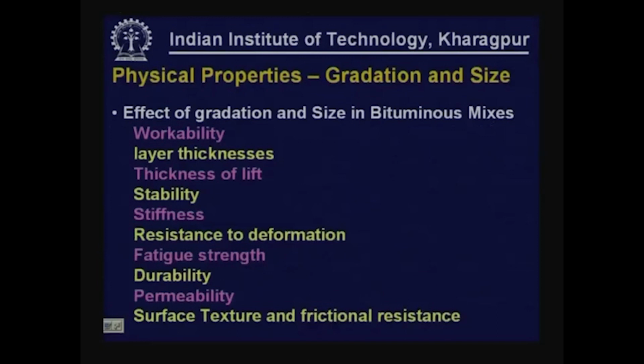The gradation and size, when we refer to size, we are talking about the maximum size of the aggregate. The gradation and size also affect the stability of the mixes. It affects the stiffness of the bituminous mix. They affect the resistance to deformation of these mixes when they are subjected to load.